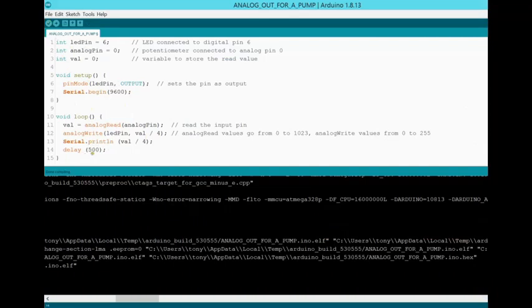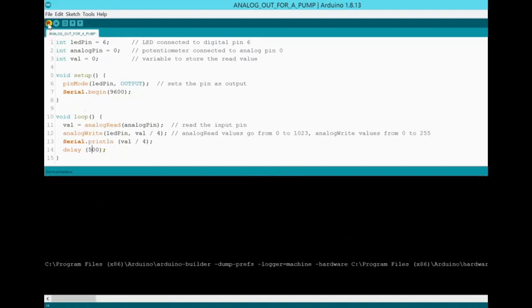Let's say that you want to do an analog read and get the average of that analog read. In that case you have a big delay within the loop, but that will not affect the frequency of your pulses, which is great. So I put 500. Let's generate this.